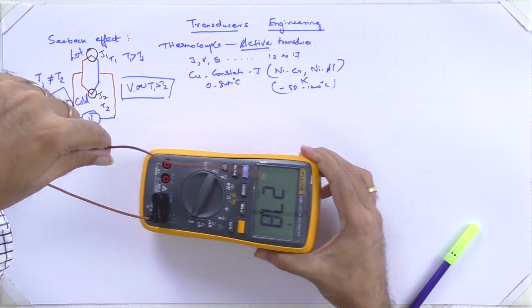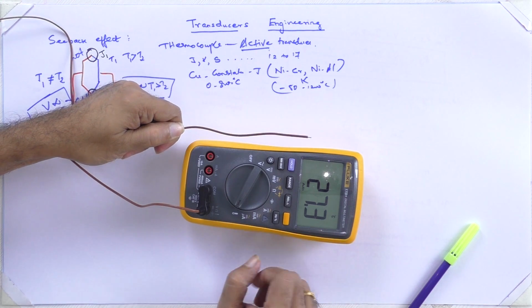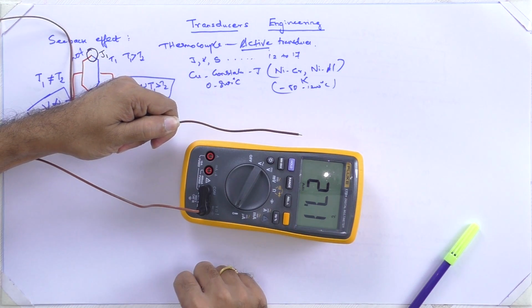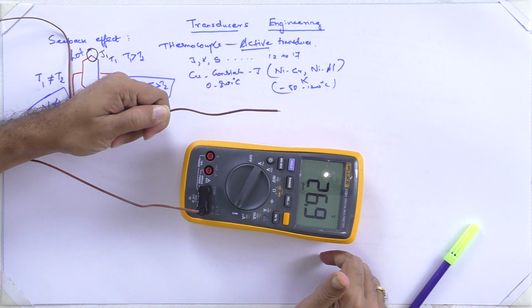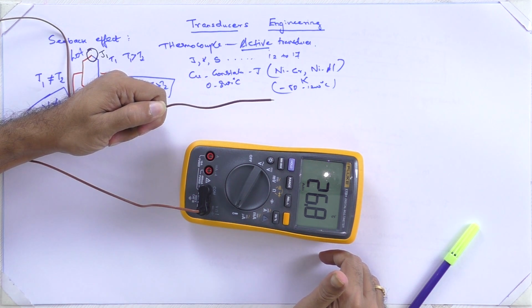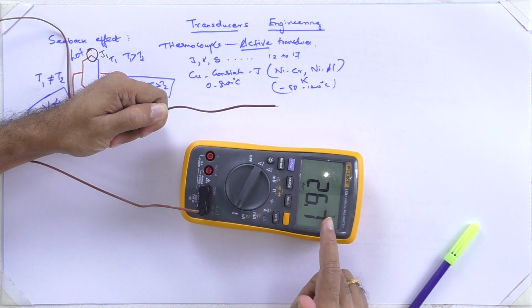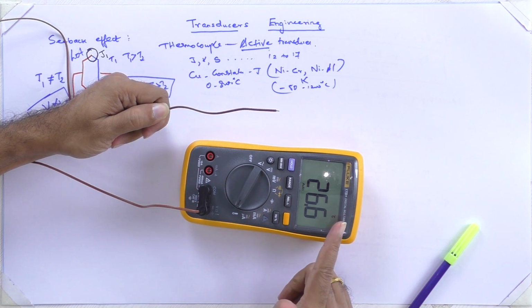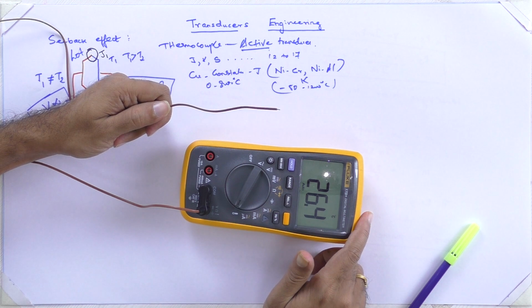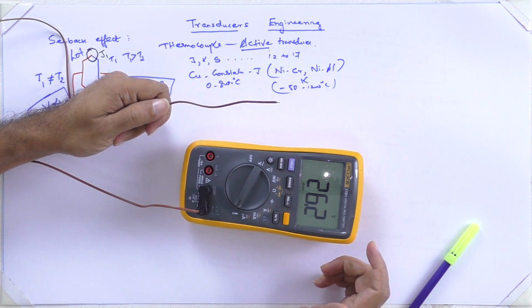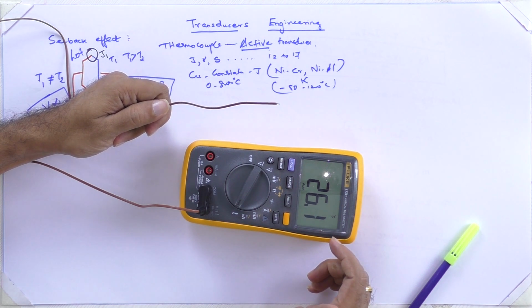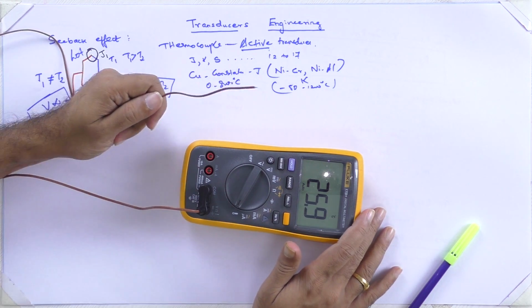Yes, it's perfectly displaying the room temperature. 27.0 is being displayed. This is the room temperature you have now inside this room. If you want to compare and see, you have to take a laboratory thermometer. As I told you in the first unit, you have to take 10 readings for every 2 minutes, and then whatever kind of error you have can be calculated, and whether it is a linear combination can be checked using this single sensor.